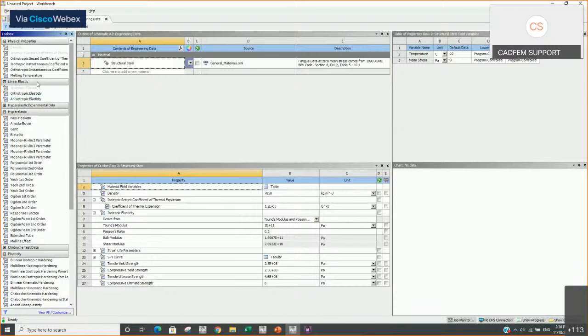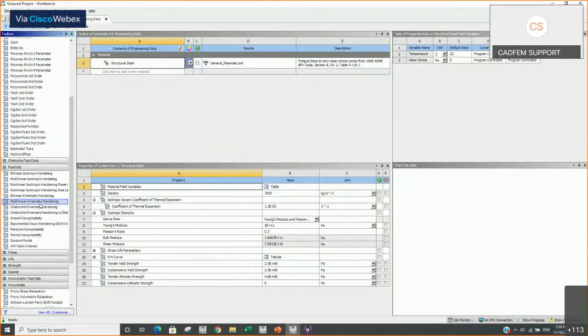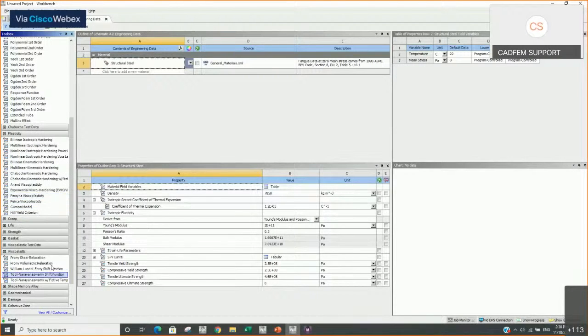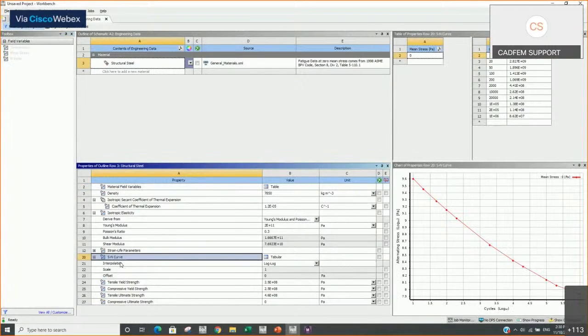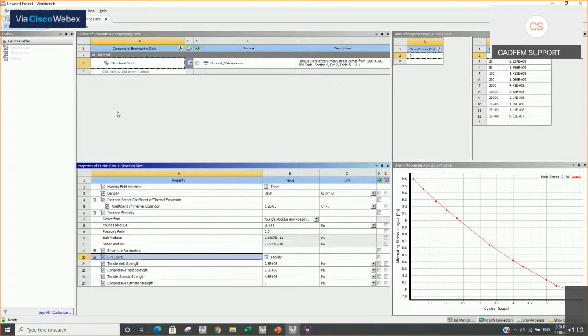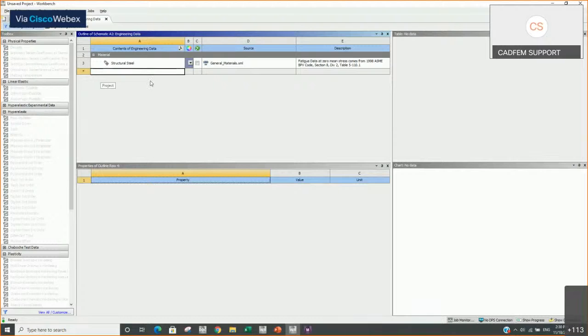Material modeling is there, temperature-wise. These are basically highly nonlinear material models, used to understand different kinds of complex materials like foam or shape memory foams and all. You can actually model them inside this. Then, in order to do fatigue analysis, the most important thing is the SN curve, the stress versus number of cycles curve. All those kinds of material data are provided here. So if you want to add any new one, you can enter it here.